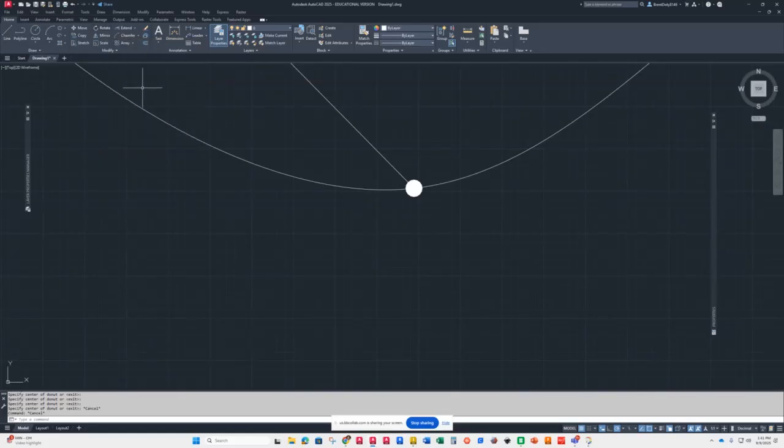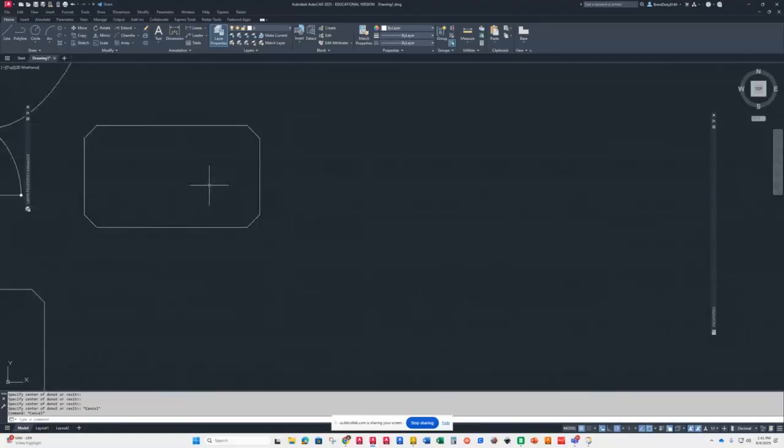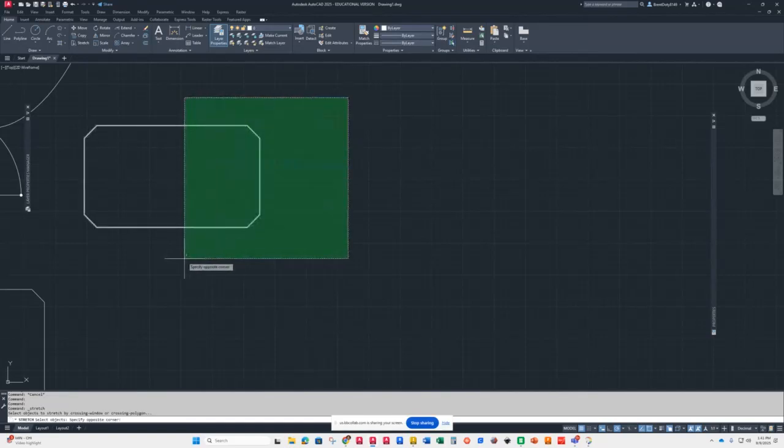All right. Okay, so let's go with stretch. How do we use stretch? Okay, remember I mentioned that some commands require you to use a certain window. Okay, so that means that for stretch, you have to start on the right and go left, part way across the object that you want to make bigger or smaller.